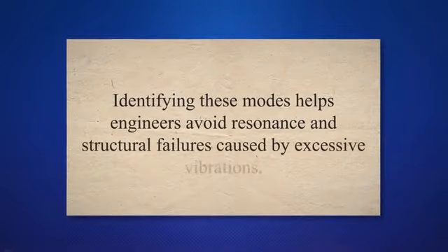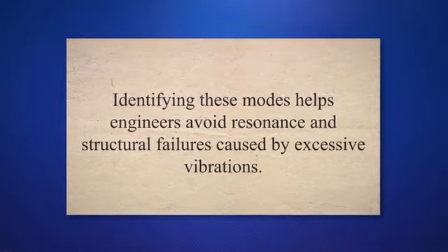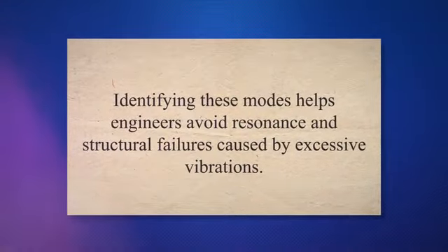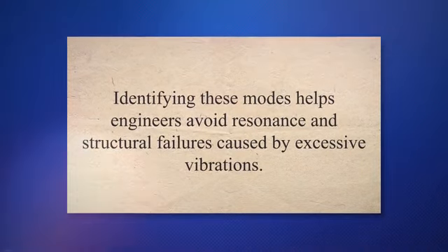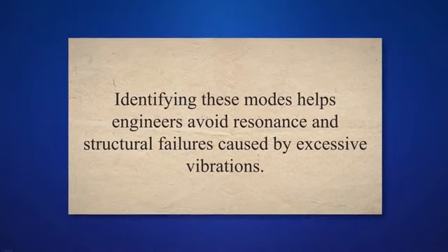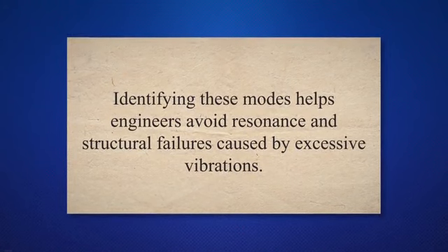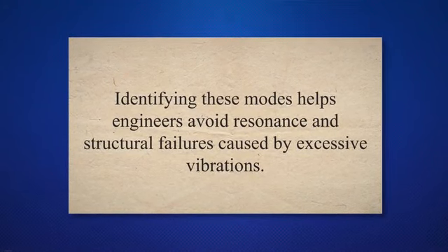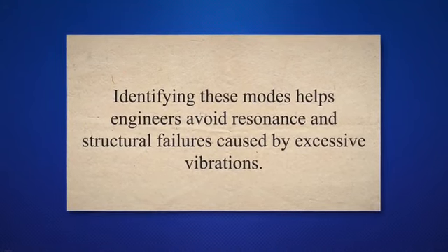Modal analysis determines the natural frequencies and mode shapes of the piping system. Identifying these modes helps engineers avoid resonance and structural failures caused by excessive vibrations. This analysis type is crucial for systems sensitive to dynamic forces.